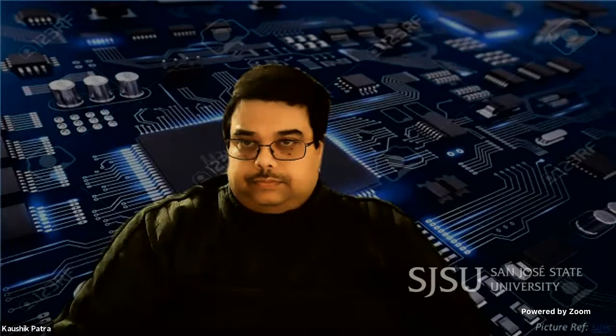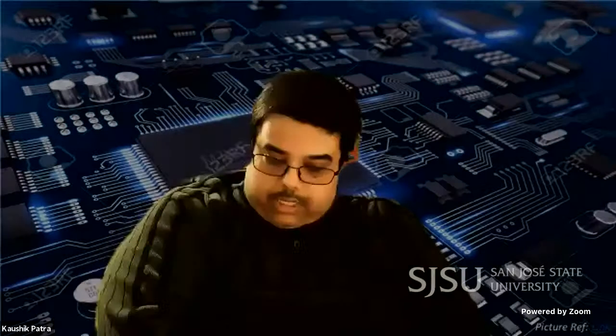Anything else? I had a question about a mux in the register file. You have it so that if the read is 0, the mux should give high Z. But the way the wiring works, it can only give an X value. Because if you put a high Z into a mux, it goes through an OR gate or an AND gate, and that gives an X.